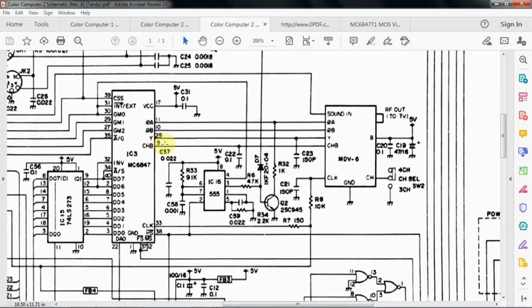Now this reference is the reference that's used inside the MC6847 to make those difference voltages. So they just go ahead and bring that signal over to the MC1372 as well, and that's so that if there's any temperature drift or drift over time, it just helps tie these two chips together better to send that reference over there.